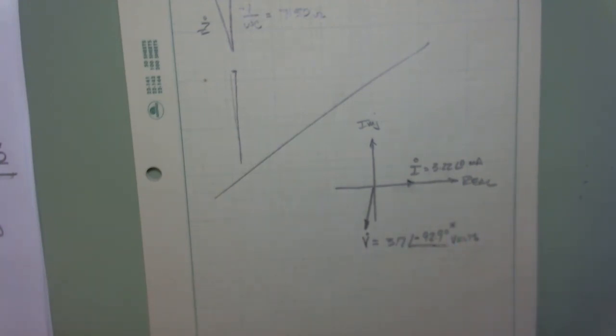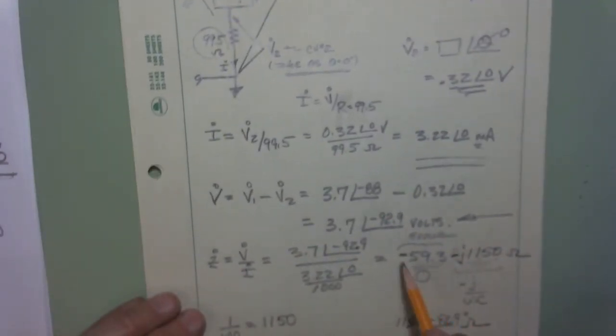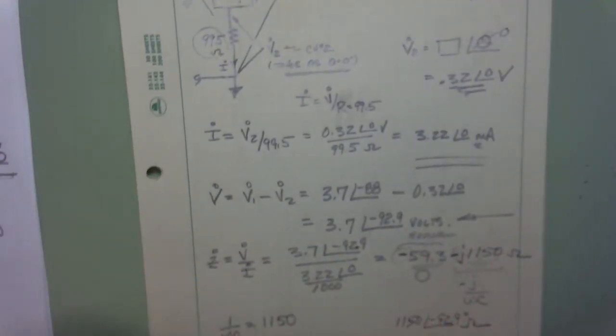But if I look at this then, what do I have here? I've got the current. The current is leading the voltage, right? So what do we have? ICE. We know this is a capacitor. So the pieces are all fitting together then. Okay? Well, I think the reason that I did this one is it's probably the most difficult one because you end up with this trouble here.